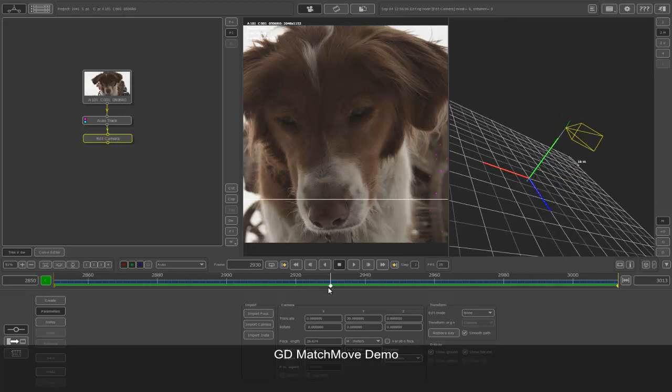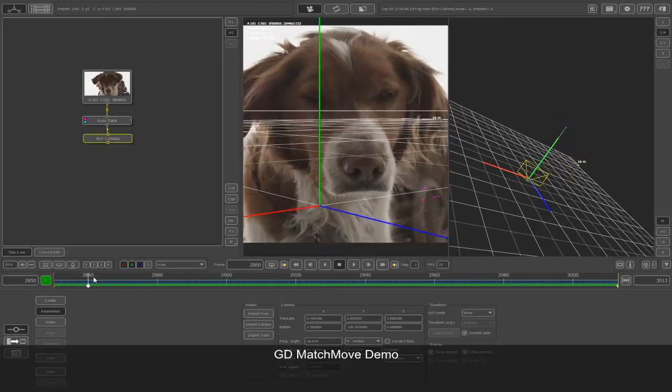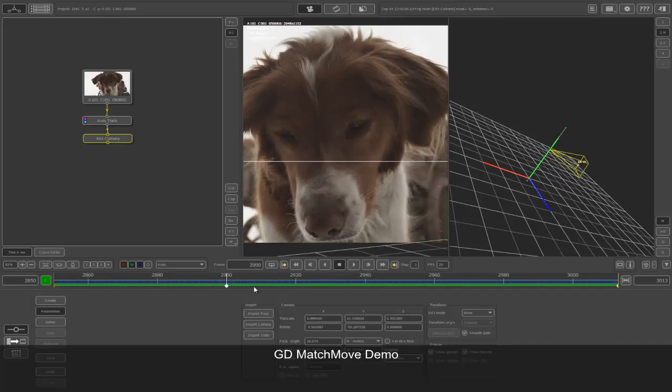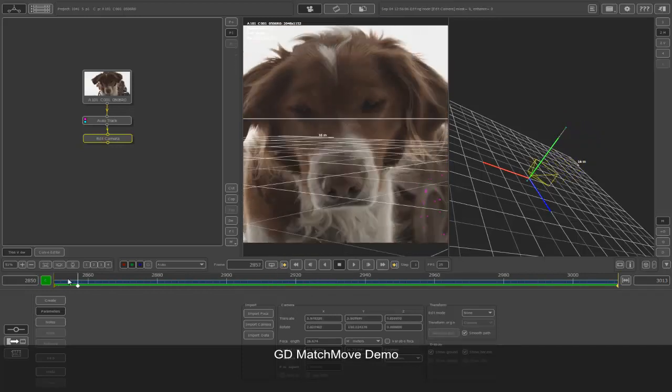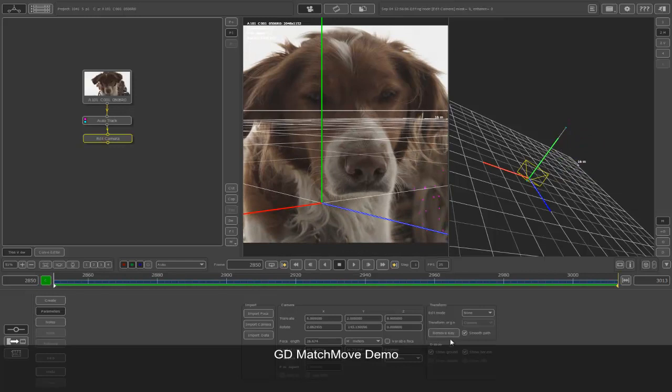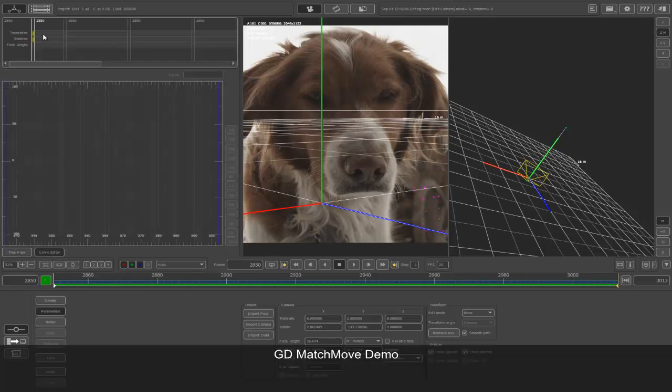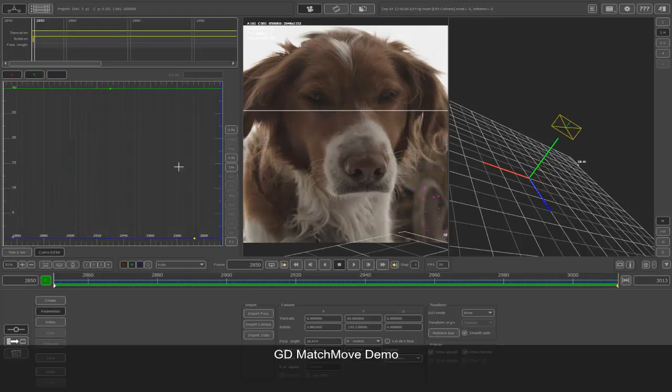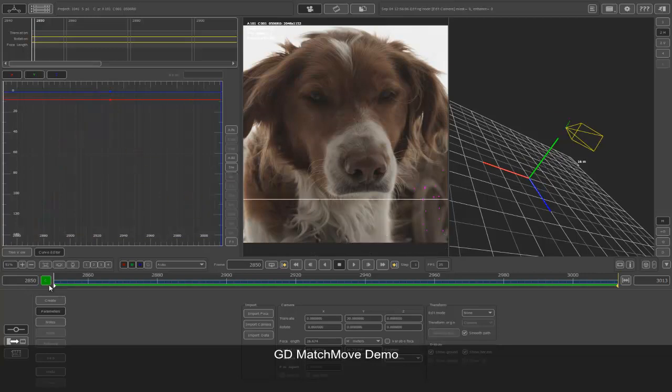But the thing is, it's moving right now, and this is a problem I've seen a lot, which is the reason I put it in. The only thing we have to do is go back to the frame where it's actually keyed and hit remove keyframe, and that removes it. Or, if you do not know where the keyframe is placed, since you can't see any keyframes here, go into your curve editor, choose the values which you have actually keyed, and you can see the curves for them. You can select the points which you do not require and hit delete, which basically resets the camera too. We also have rotation keyframes here, so I'm going to reset those as well. There are several ways to reset it, and all of them work the same way.